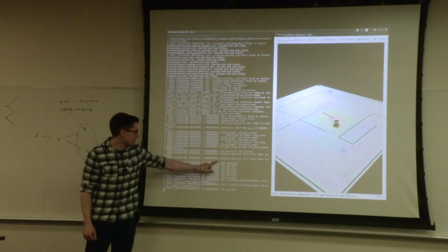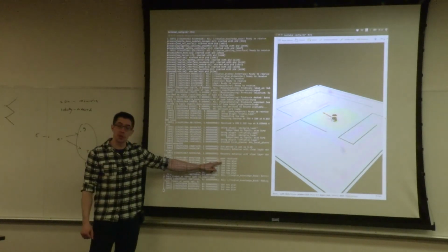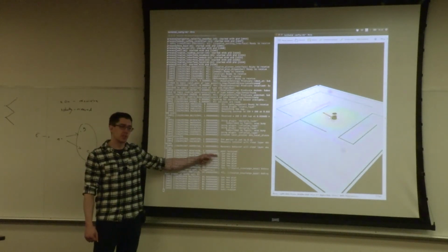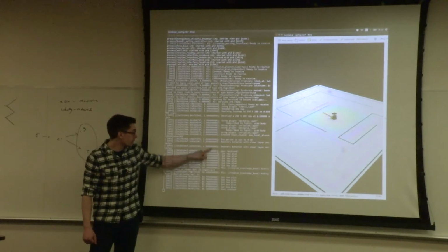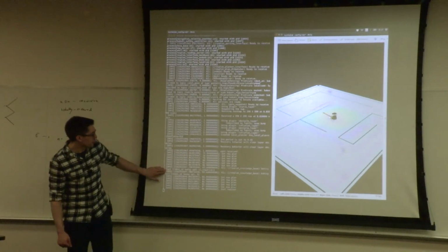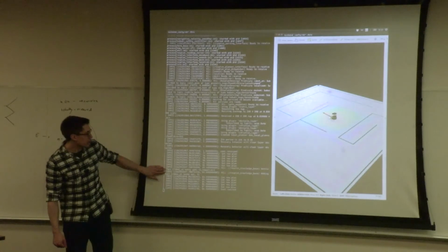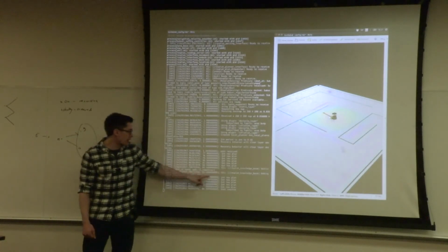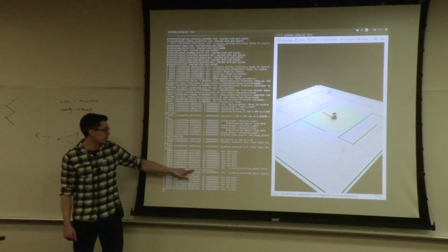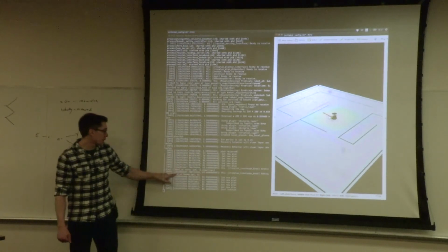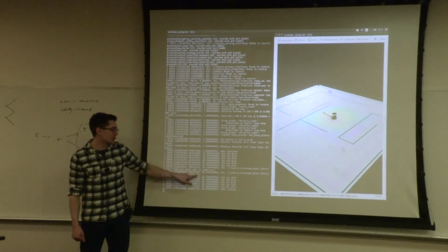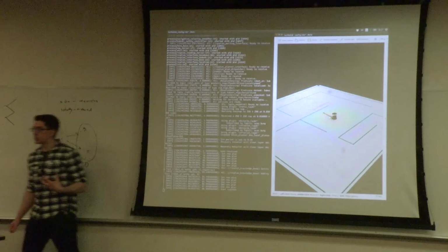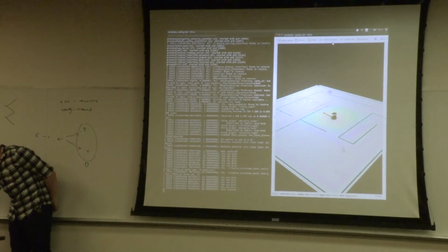Odom received, got new plan is referring to MoveBase publishing these messages. This is referring to the navigation plan, the path. At some point, as it was moving through the door, we got a couple of messages from the knowledge base: setting robot at waypoint 0 is negative equals 1, and robot at waypoint 1 is negative equals 0. So the position of the robot has now changed in the knowledge base.